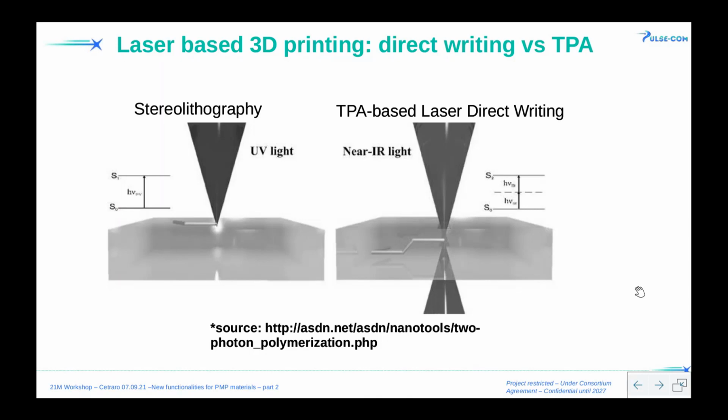I've chosen this schematic representation because it has the most important parameters for any kind of laser processing. In most laser processing, be it laser ablation, welding, cutting, and all of that, you have linear interaction, and that means you focus the incident laser light at the surface of the target. Then we have linear interaction at the surface, depending on the application, and that's pretty much it.